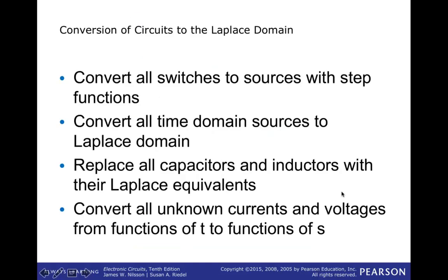All right, well, there's a sequence that you go through when you want to convert circuits to the Laplace domain. You don't have to do the steps all in exactly the same order. So the first thing you want to do is convert all the switches to sources with step functions. In the time domain, we often will have a DC source that's switched on or off. In the Laplace domain, you want to represent that first in the time domain as a source with a step, and then you can transform the step function to 1 over S in the Laplace domain.